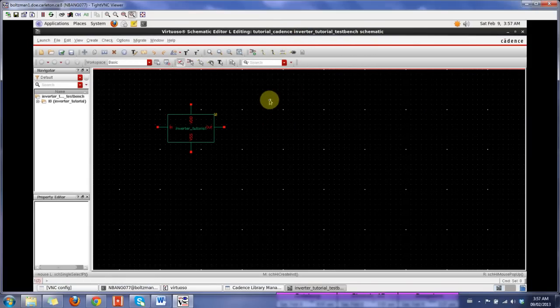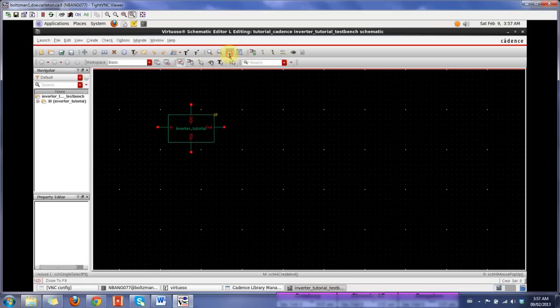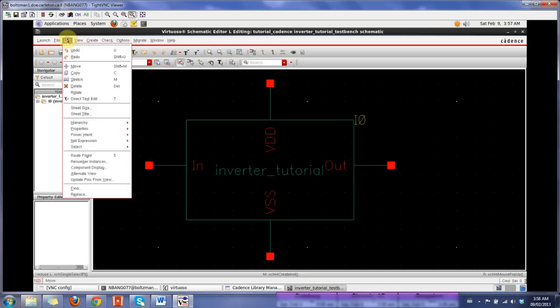Now there are a few navigation tips I'd like to give in Cadence. When you're doing a big design, you tend to zoom in or zoom out of the design. We use these nice little options to zoom in, or commands to zoom out, or you could even fit to the whole screen. The bind keys are given here.